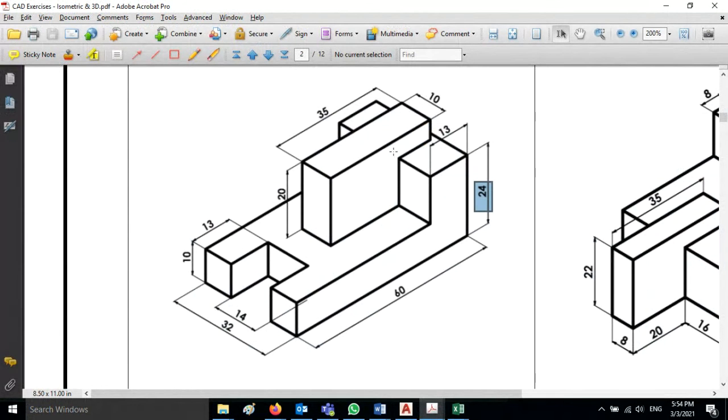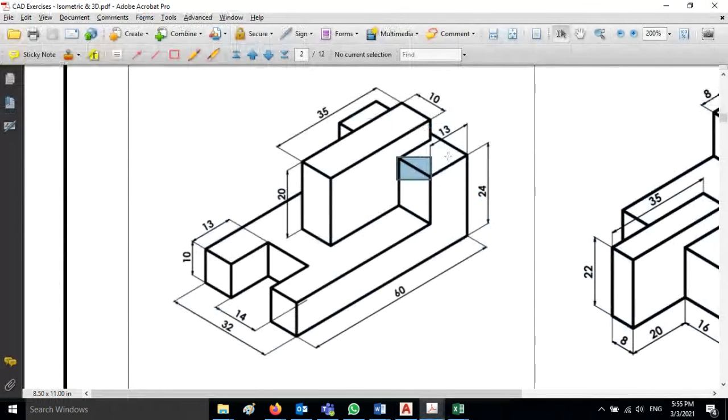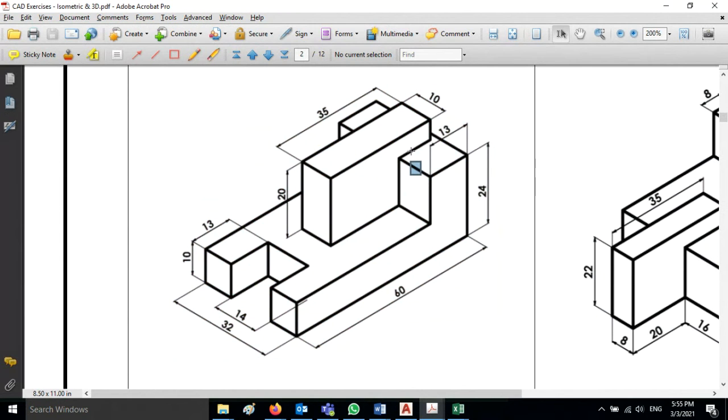Next, we can also draw this line. Okay. Now, what is the distance given from here to here? Anything given? Nothing. Here only 10. Here we have 32. Then what is remaining? 32 minus 10, 22. 22 means from here 11. This line is 11. Therefore, I can draw this line 11. From here, press F5 and draw 11 millimeter. And then I can draw this line. This line I have drawn. Now I have drawn this line. Next I will draw this one.